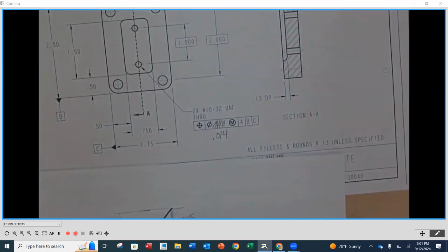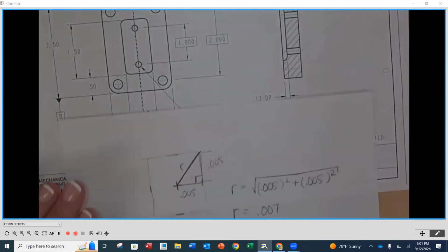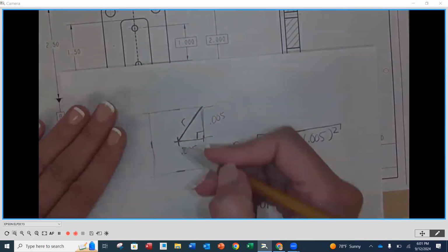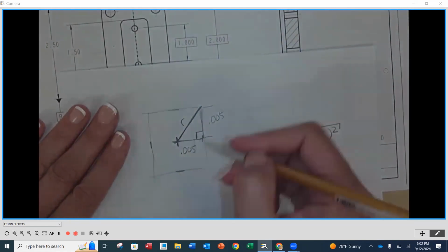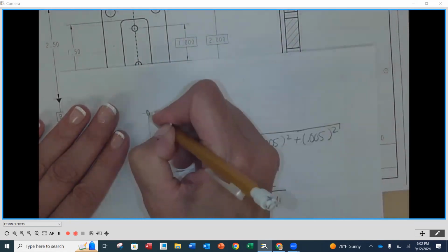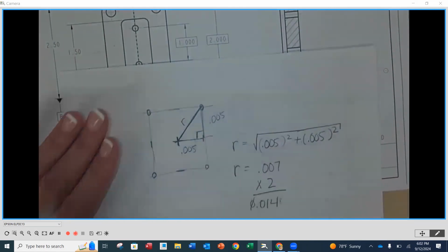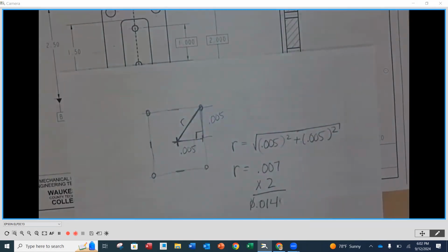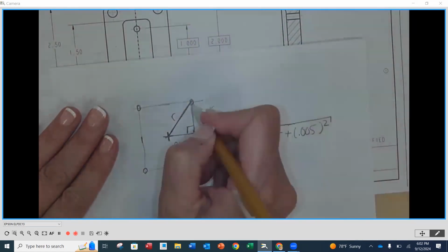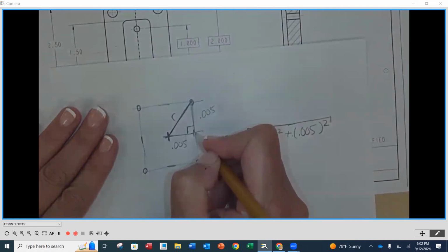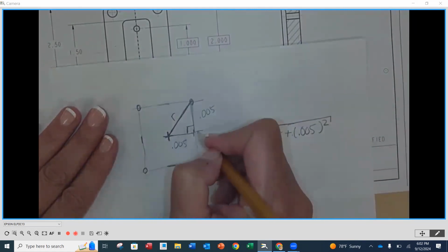That converts the rectangular tolerance zone here to a circular one. So if you recall, when we looked at this back in GD&T, if this is my nominal value and we did a plus or minus 5 thousandths, you remember how we said, if these 4 corners work okay, that means that the radius going here, if that's 14 thousandths, or I'm sorry, 7 thousandths, that's more than 5 thousandths.